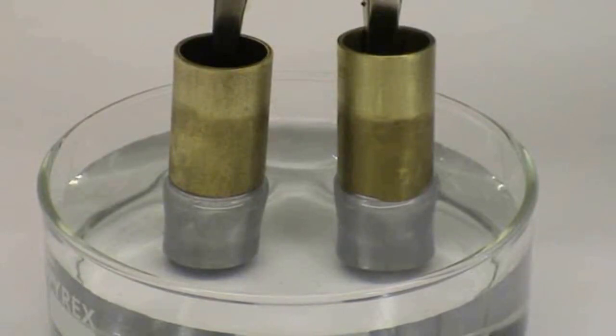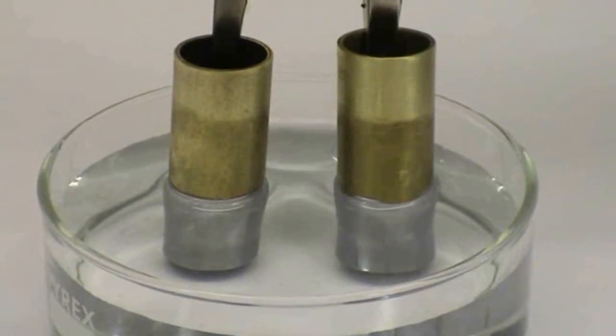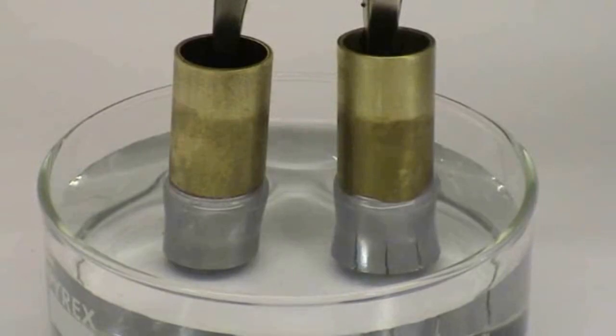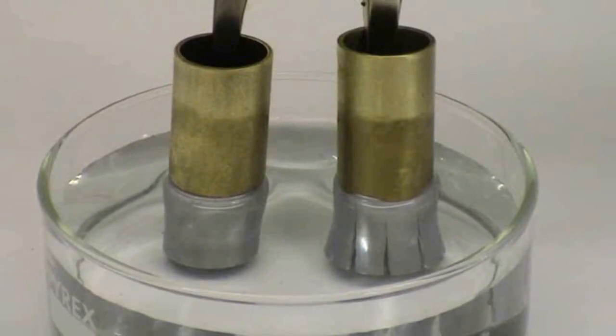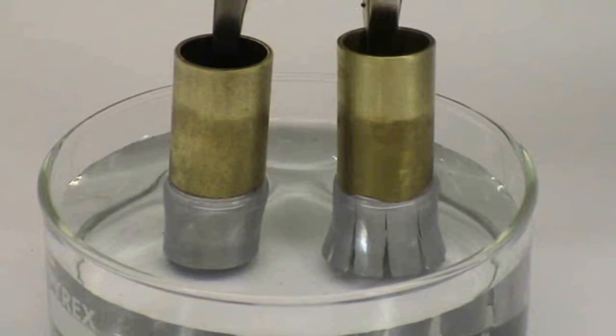As the cracks appear, they also accelerate as there is now a faster route for mercury to get into the brass. While the cartridge on the left has the same microstructure and has been exposed to the same environment, there is nothing to drive a crack. This is a bit of a parlor trick, but it does demonstrate what can happen in other corrosive environments with a susceptible microstructure.